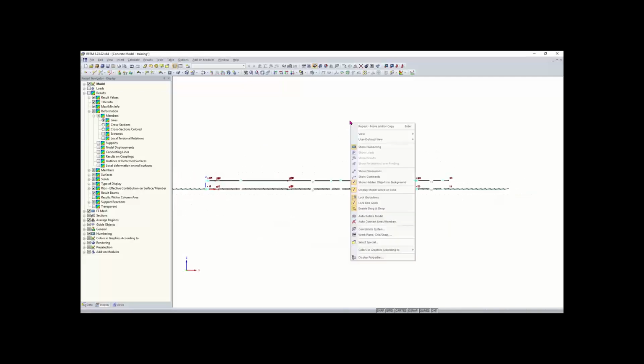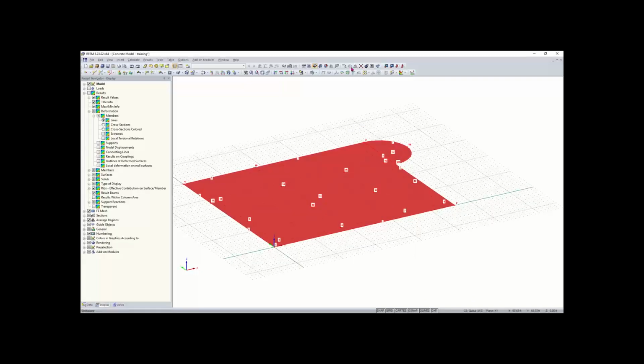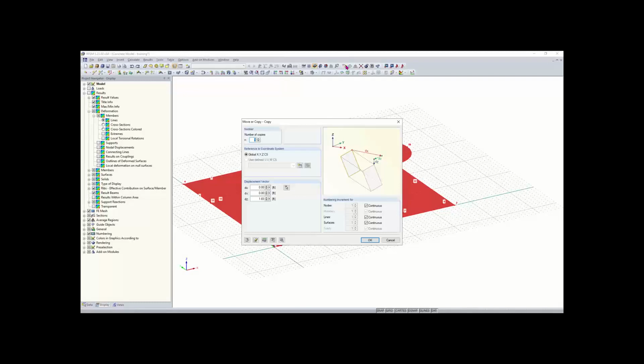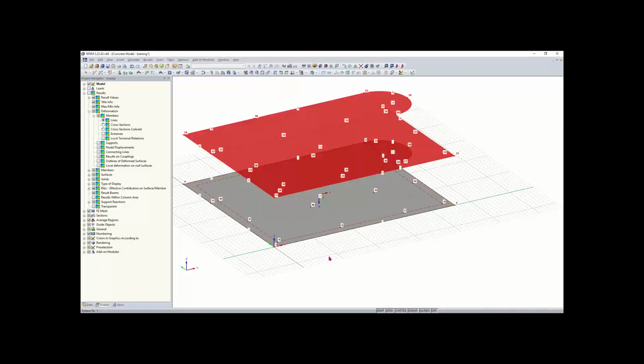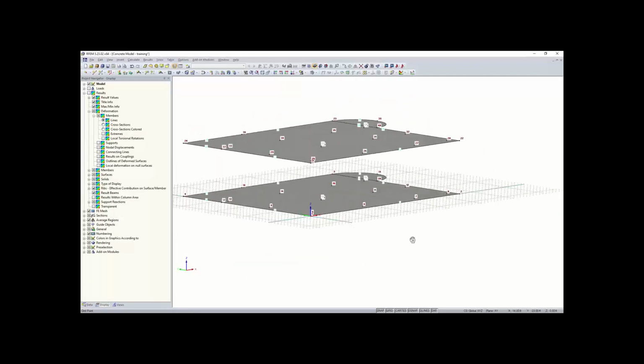So to change that, I can Control Z and I'm going to redo that. Move copy. Oh, I typed in 1.83. That makes sense. So 11.83 is what we want. And now our ceiling slab is created with the correct distance between them.